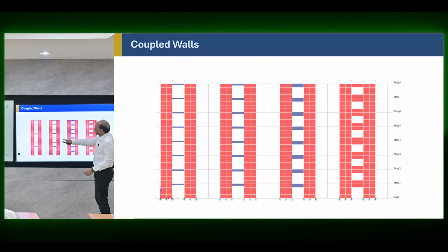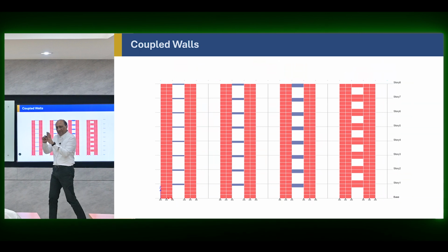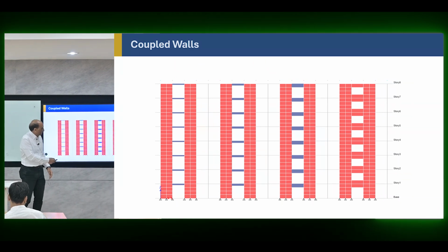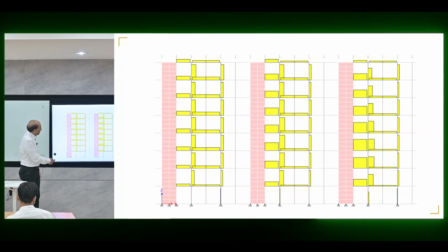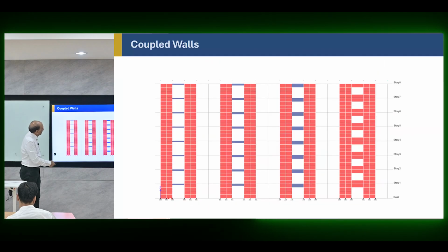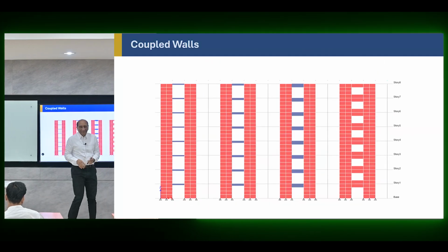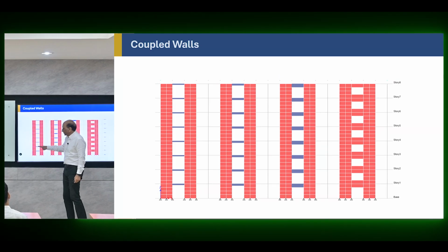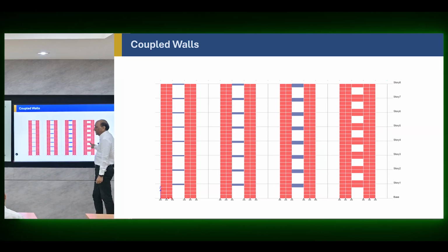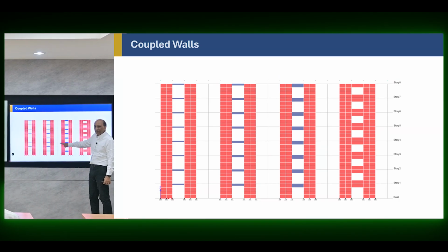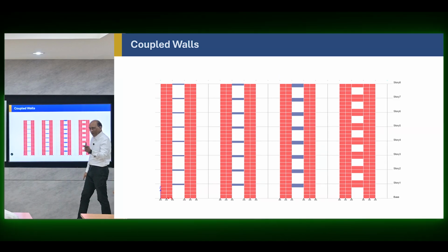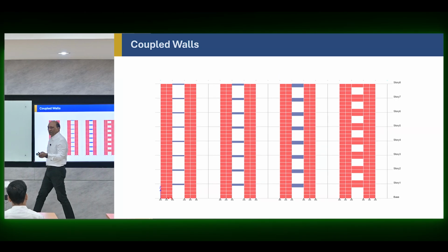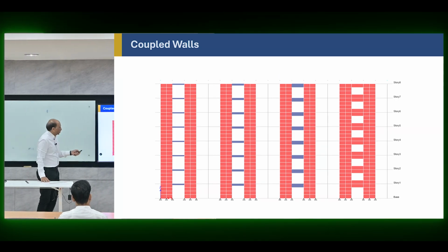So same thing we can do with coupled walls. That one was coupling between a frame and a wall, the previous example. We can do the same thing. We can take 2 walls, and this is the key. Take 2 walls here, with this simple slab connection, beam connection, deeper and deeper, right? You put deeper beams to connect them, coupling beam couplers between walls, not between wall and frame. And you have the same advantage as I showed you earlier.